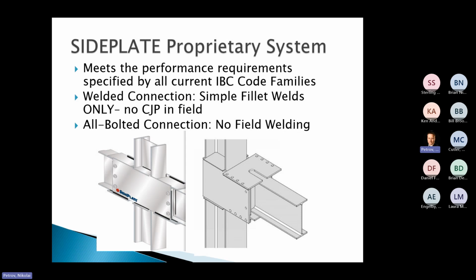They've tested this throughout the process over and over again to show that they have the ductility. And you also have the ability to develop plastic hinge in your beam without causing any sort of brittle or fracture failure in your beam because your beam extends into the plated connection a certain distance. And so that is kind of the long and short of their system.